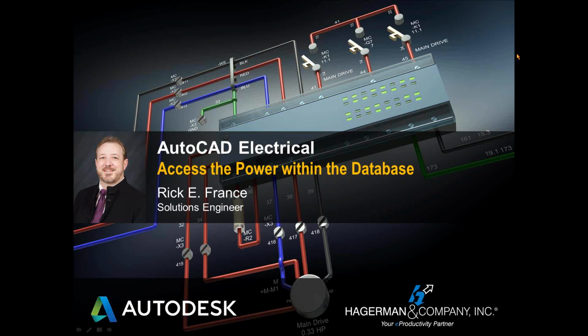So right here I'm going to place a push button into my drawing. When I go to the lookup here, you'll see the default that it goes to, which many of you have probably seen 100 times if you've been using AutoCAD Electrical, is the Allen Bradley 30.5 millimeter extended red. So that's the default we're talking about first, and how to change that. Unfortunately, there's nothing inside AutoCAD Electrical that allows you to change those defaults. You have to do this in Microsoft Access.